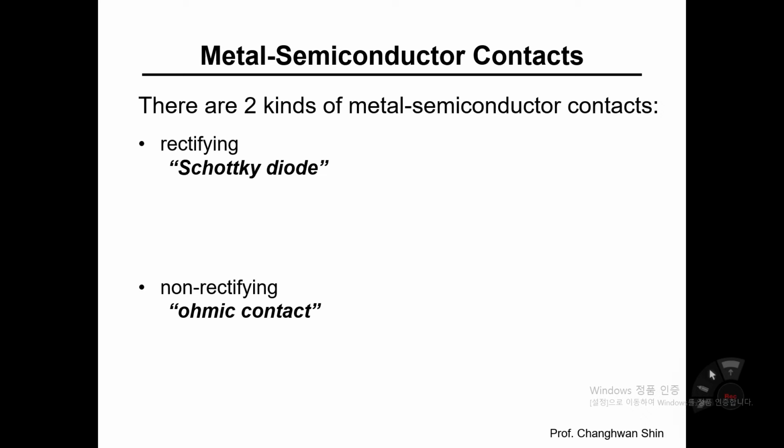However, once the metal-semiconductor voltage difference is negative, in other words, a reverse bias is applied onto the MS contact or Schottky diode, then the total amount of current flow through the Schottky diode is very minimal, negligible. So unidirectional current flow can be achieved and implemented in a Schottky diode. That is the reason why we are saying that this is a diode. The basic role of a diode is to rectify or direct the current, in which direction the current is flowing in a diode.